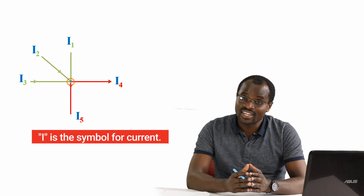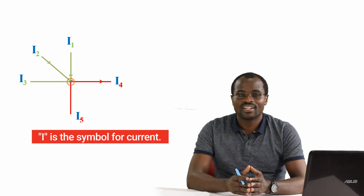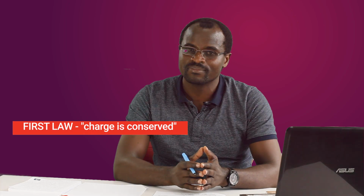Now let's consider a junction with 5 wires. 3 of these wires are carrying current into this junction. Let's call them I1, I2, and I3, where I is the symbol for current. 2 of these wires are carrying current away from this junction, and let's call them I4 and I5. Going by this law, the sum of I1, I2, and I3 must be equal to the sum of I4 and I5. In this first law, charge is conserved.